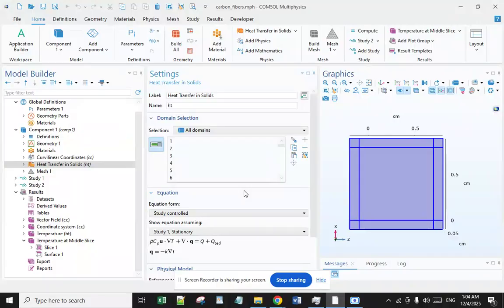Single-sided constant temperature heat transfer experiments show that the average steady state temperature of the specimens increases with increasing nanofiller mass fraction, reaching enhancement of 18.71% for 3 weight percent GNPs, 10.45% for 3 weight percent CNTs, and 2.57% for 3 weight percent nano ZnO.